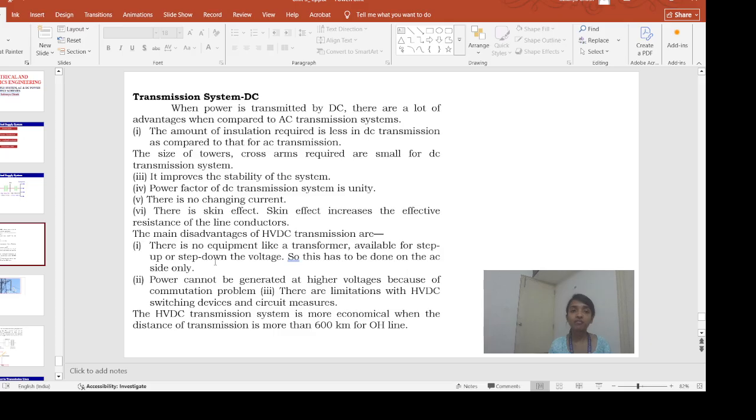Because when we give the AC power at the input side, at the primary winding of the transformer, we will have some alternating magnetic field. Now, due to Faraday's law of electromagnetic induction, that alternating magnetic field in the primary will induce some EMF in the secondary winding.